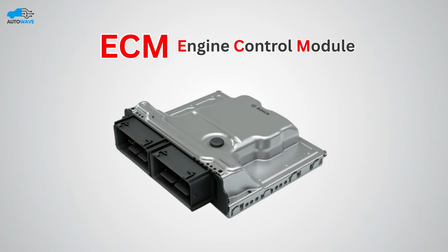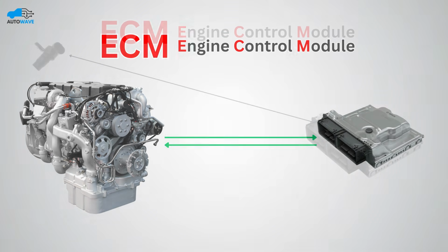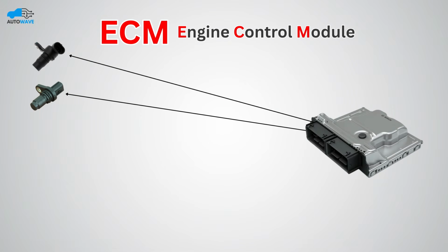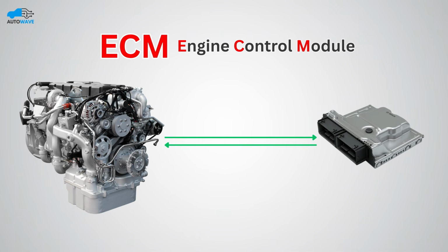ECM full form is Engine Control Module. ECM is responsible for all parts of the engine. All sensors on the engine, like camshaft position sensor, crankshaft position sensor, MAP sensor, oxygen sensor, coolant temperature sensor, and others, are controlled by this unit. This ECU gives power supply to every sensor and receives output in return, so that different engine operations like fuel injection, ignition timing, air-fuel ratio, idle speed, and others can be controlled.